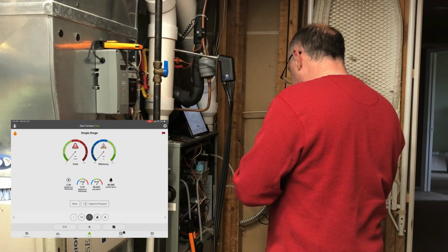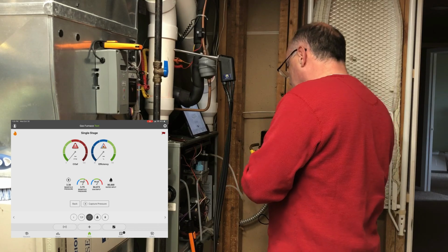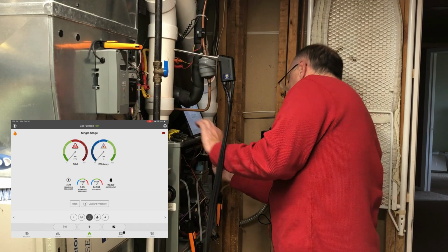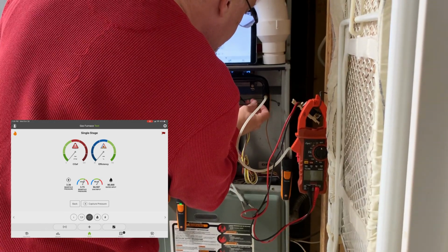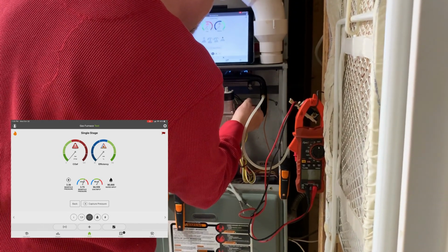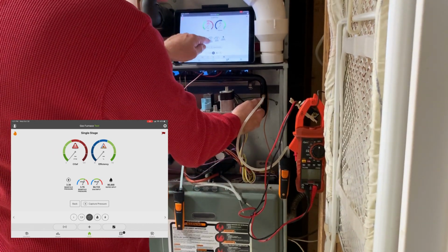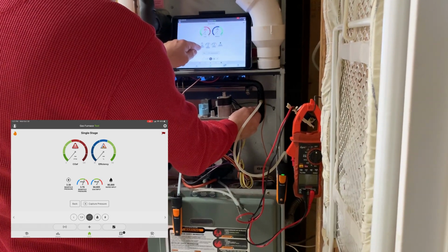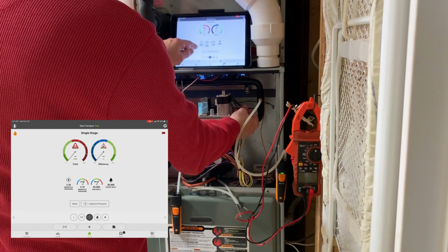After I pull out the, just got to make sure I get the right Allen wrench here. I'm thinking it's a small one here. Just get this slid in here. Yeah, that bites. So now you can see here I got my manifold pressure 3.75, and it calculated my target at 3.39. So I'm going to start slowly backing that down.